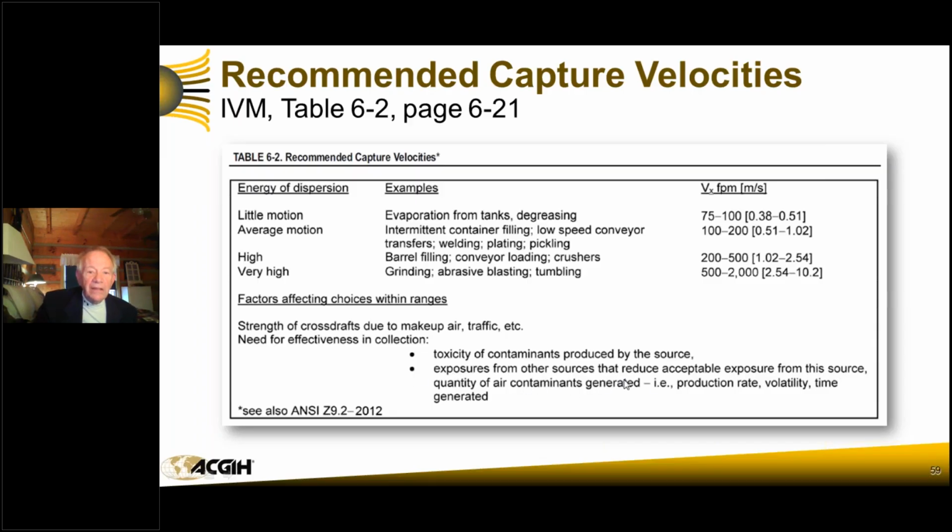The quantity of air contaminants generated, production rate, the volatility of it, how much is coming off, time generated, how is this done, how many times is this done per day? Is it done all the time? How much time does the employee spend at that station? These are very important parts.